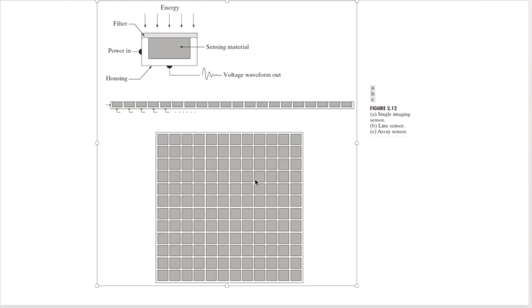And that has a line array sensor under it. And it knows how fast it's feeding your document. It does the same thing that the post office does. They read it as it's passing by, right? And they just know the speed, snap the pictures fast enough, correct for the motion blur, and you're done. Okay? Good, clean, crisp image. And you can feed it much faster than stopping to take a photo. So it allows really high-speed applications. So a lot of assembly lines, manufacturing does this. It's also used in medical.